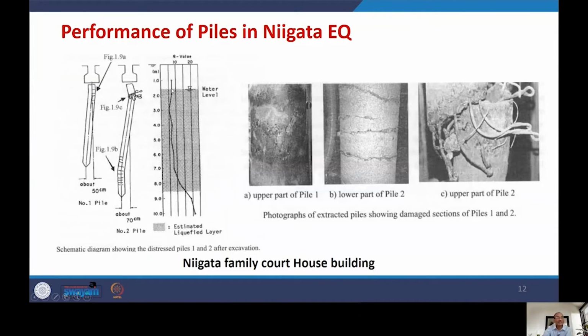And when we say N value is less, even if the N value is high at a depth of 8.5 meter or so, still it gets liquefied. So you could see that for the liquefiable soil, the value of N is somewhere between 5 to 15. It is everywhere more than 5, but N of 5 is nothing. If the N value is less than 10, then the soil condition is not good, and it is certainly expected to liquefy. So when N is 5, then you have 10 and 15 and 20. So it starts increasing from here, but because the depth is so high, the requirement is also high. But when N becomes more than 15, then the possibility of liquefaction is ruled out.